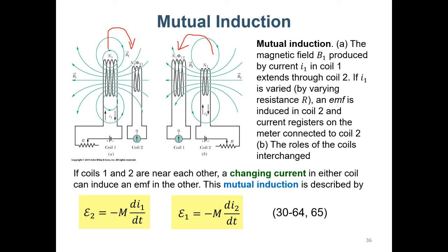we define the mutual inductance in another way. So here we have di1 dt, which means the varying of i1, which will generate an induced EMF for coil 2. So this is called a mutual inductance. For the self-inductance, it is the varying current of the coil itself, and it will change the induced EMF for itself.